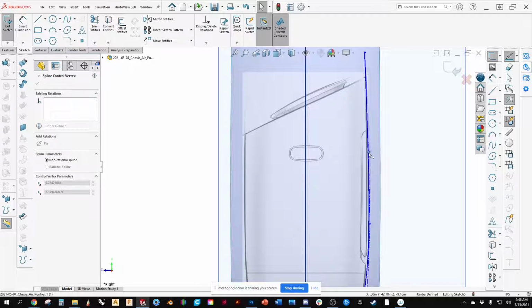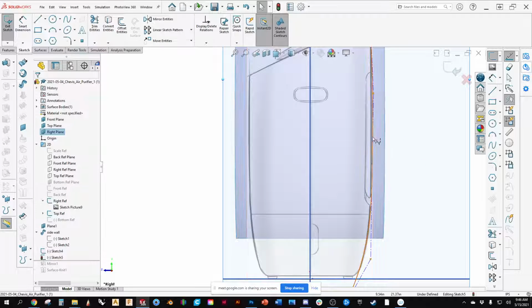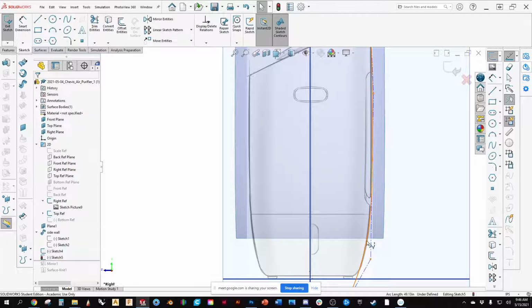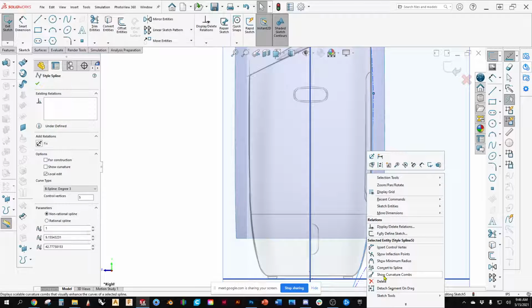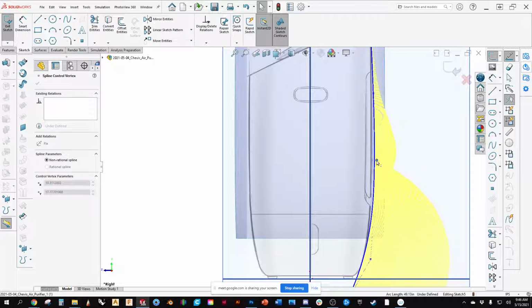Even if it looks like it's only needed as a 3 point spline, I still add 5 points, because there's always going to be that moment when you sit there and say, I want to get a little bit more curvature to this. Well, then you've got to go back in and rebuild it.